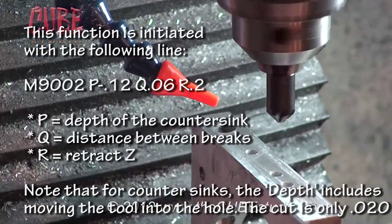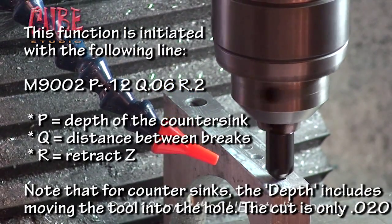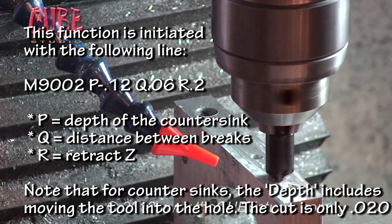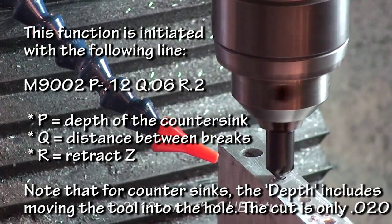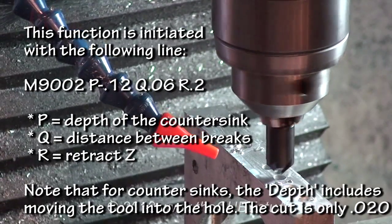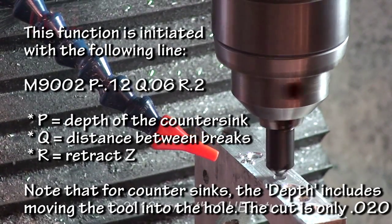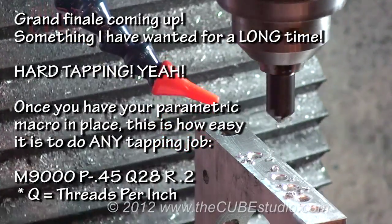This function is initiated with the following line: M9002, P minus 0.12, Q 0.06, R 0.2. P equals depth of the countersink, Q equals distance between breaks, R equals retract Z. Note that for countersinks, the depth includes moving the tool into the hole. The cut is only 20 thousandths. Grand finale coming up.